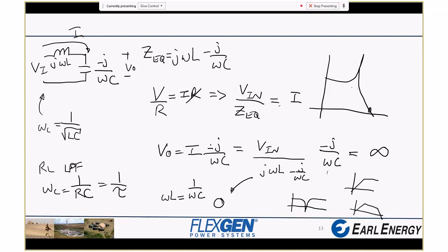Yeah, from a control perspective, and I won't get into how we accomplish it, but like I said earlier, the parasitic resistances of the L and the C make this go to less than infinity. So if I were to draw that out a little more cleanly, maybe I can draw straight lines this time. If there were little parasitic resistances in here, instead of going to infinity, this resonant peak might go like that. So it still goes above, say, the passband, but doesn't go to infinity.